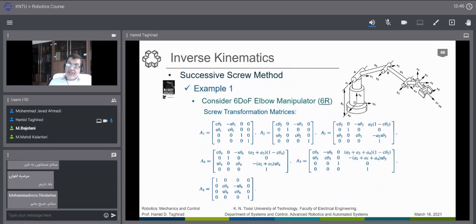The wrist is not quite as simple as in the Pieper theorem. We have only 2 intersecting axes. This point P has 2 intersecting orientations on top of each other. But the real wrist, which is at this point, actually has 1 length A, so we don't have the 3 intersecting parameters here. It is quite difficult for such general cases.